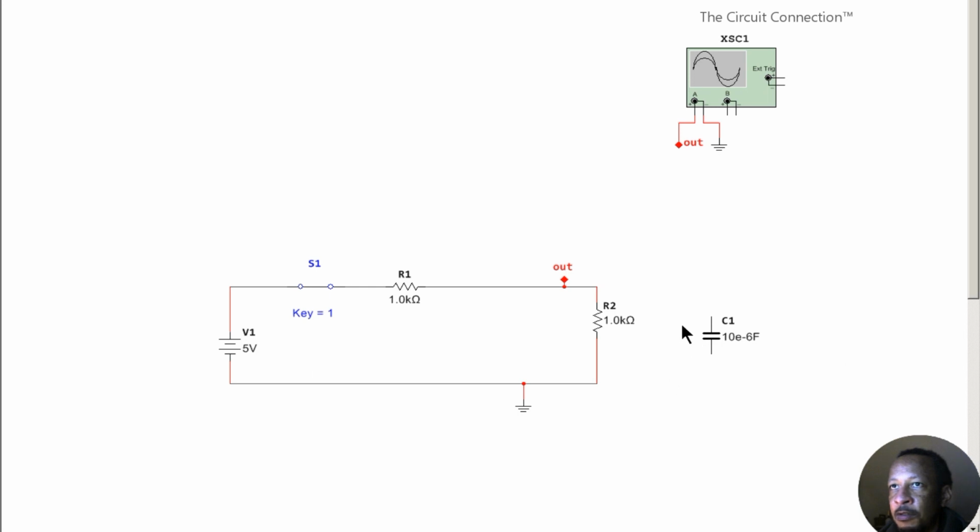Next, for the RC time constant itself, what is the net resistance of all of this going back here during the charge up? Well, that's basically the net equivalent resistance, and you find that by making your voltage source here a short. When this is shorted and you only have R1 and R2 left, that is just R1 parallel to R2 for what C1 is going to be subjected to as an equivalent resistance. R1 parallel to R2 is just going to be half of this amount, because R1 and R2 are both 1K, and it's half of that value when you calculate them in parallel. And so you're going to get 500 ohms.